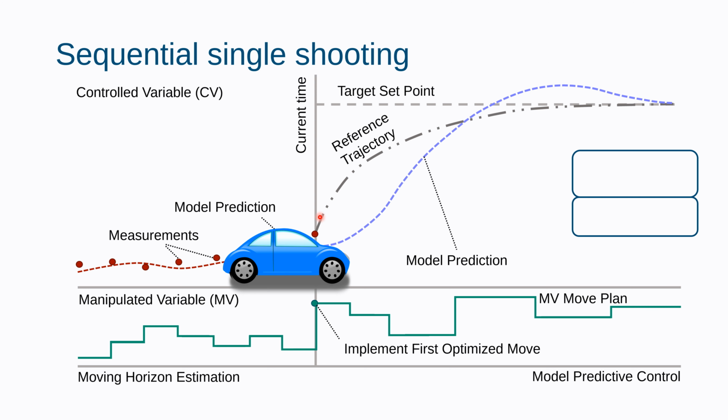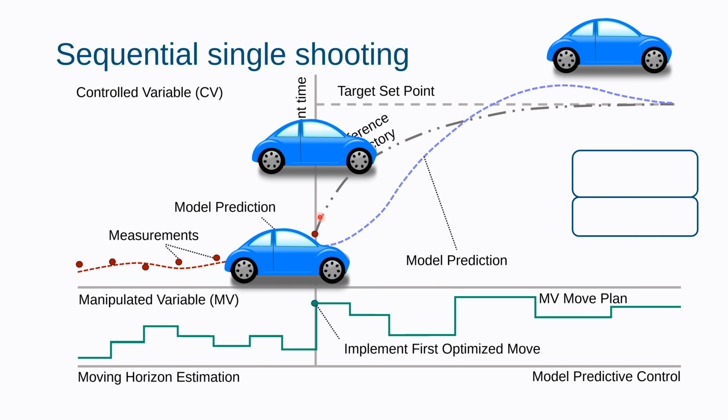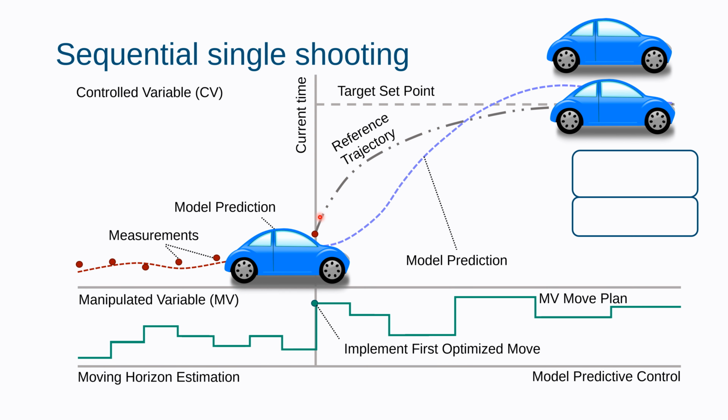All right, so we talk about the sequential or single shooting method. It's like you have a guess on the reflux ratio, and you figure out that maybe you're too high. So you have another guess, and maybe you're just a little bit too low. And so you continue this process, getting information about whether you guessed too high or too low and make those corrections. In this case, you're evaluating the model equations and the objective function separately.